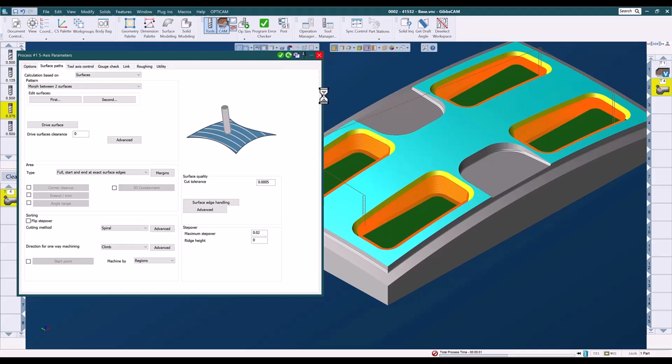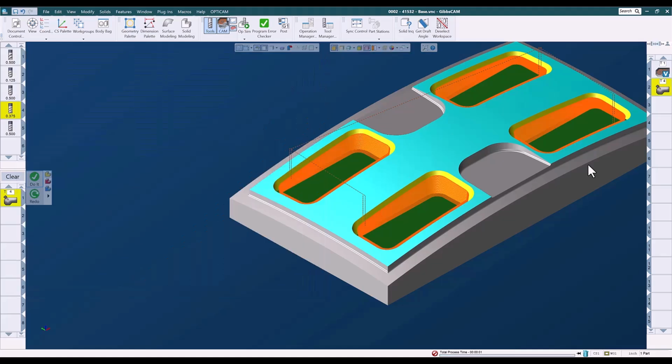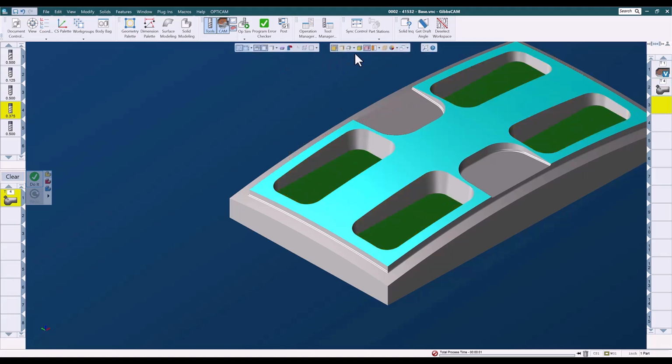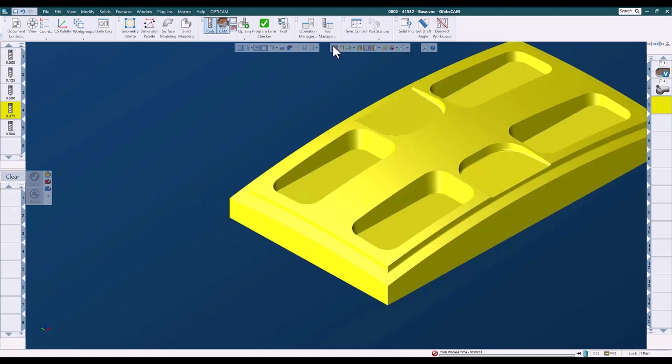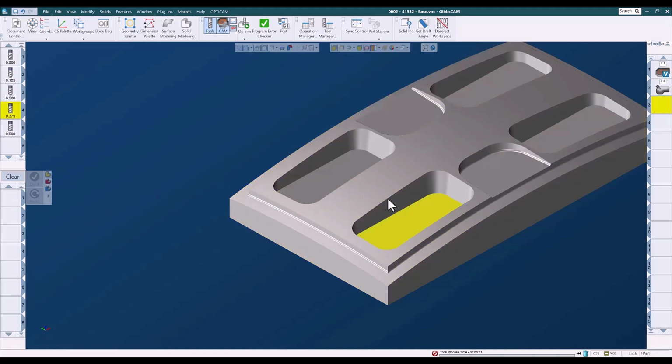And there's that toolpath. I'm fairly pleased with that. Blank tile, blank area of the screen, and let's deselect and decide what we want to do next. I think that I will machine the flats next. That is definitely going to only be these floors here. But a part of many of my 3D parts is a flats cut, which automatically finds any flat horizontal surfaces and finishes them.